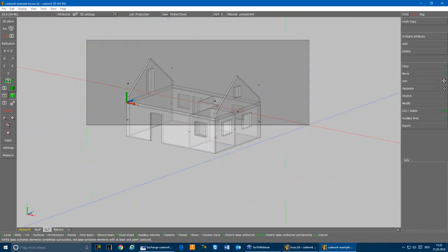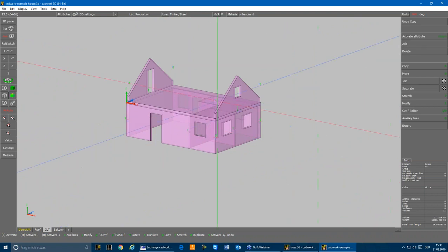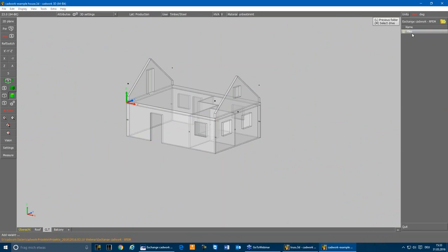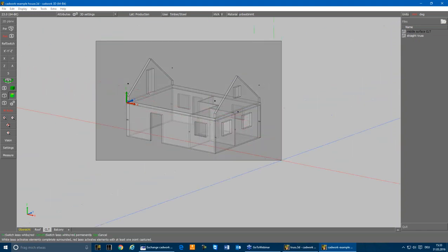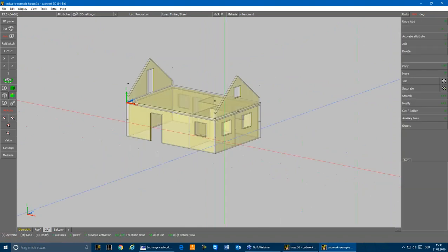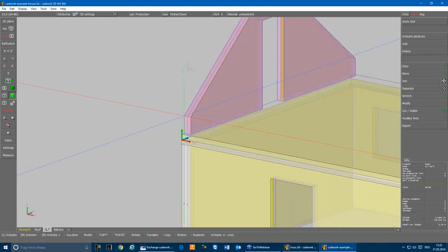To define this, we just created a small variant tool again, which is in Add, Variants, current folder in this case. We call this one Middle Surface CLT. So anybody who wants this file, just write a mail to info@cadwork.de or to your connected cadwork reseller, and we will send the variant file to everybody. This is just a small variant that, when I define all the parts, creates surfaces right in the middle of each element.